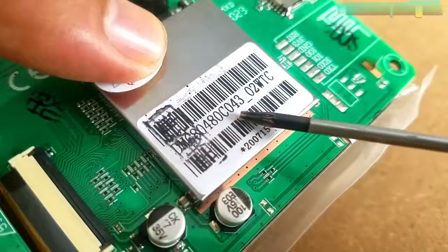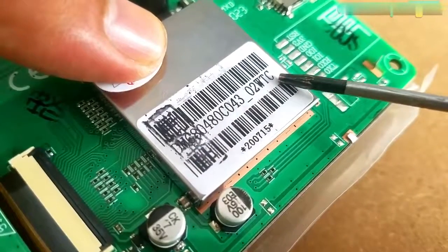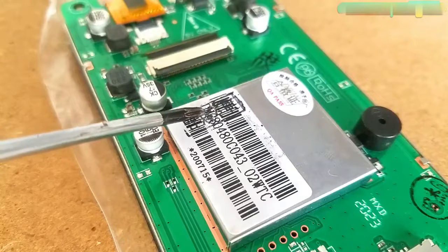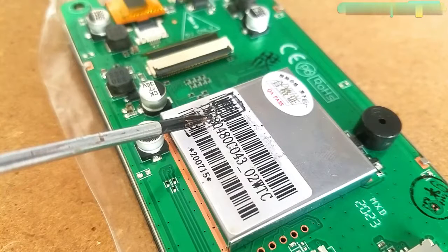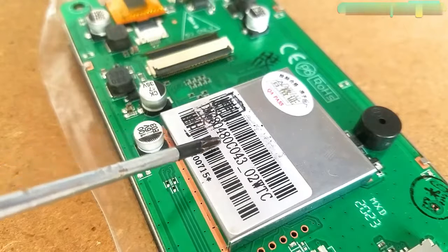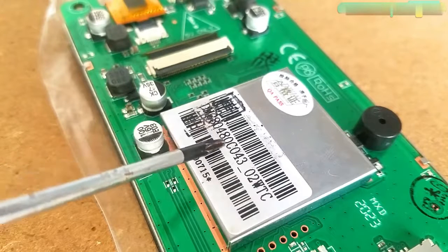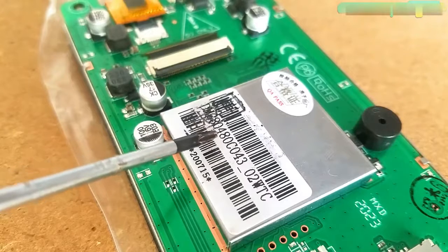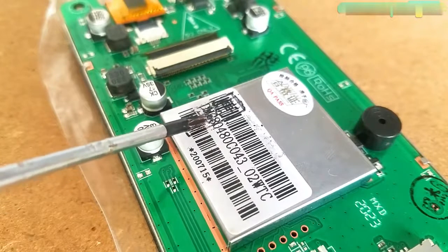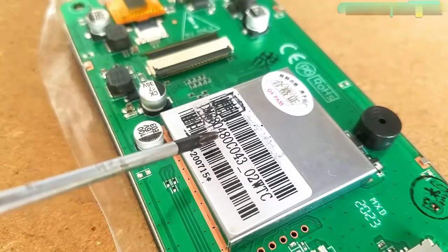The DWIN Smart LCMs follow a naming rule. The first 2 characters DM represent the product line code. The third character represents the color code. For this touchscreen, G means 16.7 million color. The next 5 digits represent the touchscreen resolution. For this touchscreen, 80480 means this is 800 by 480.